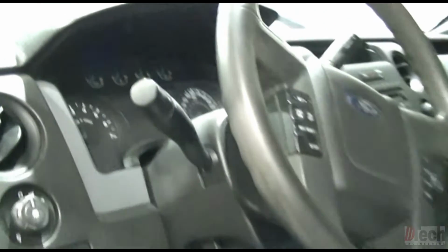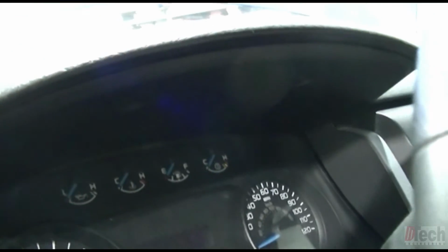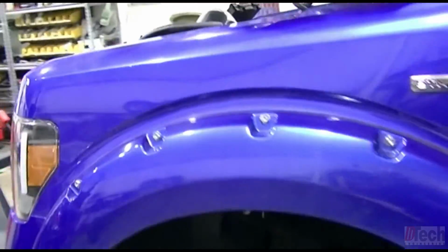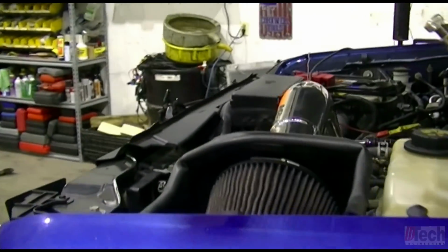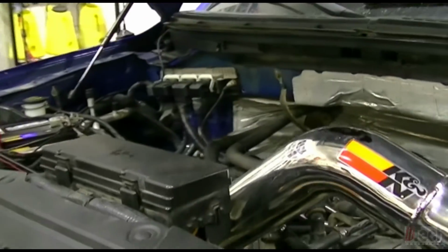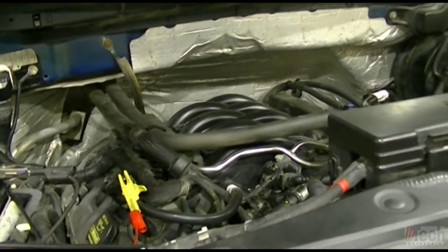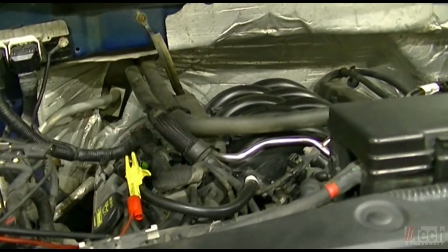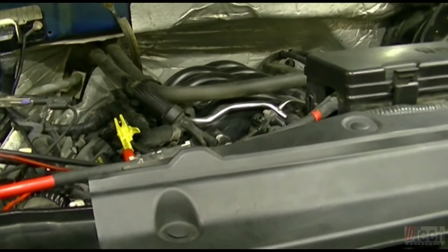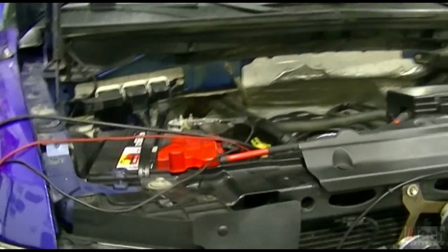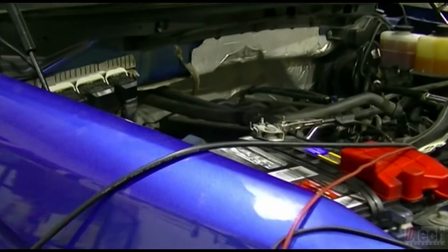As far as what this vehicle sounds like when it runs, we'll get you a shot of that. You can kind of tell it doesn't run terrible. It's not like a dead hole type of misfire. It's sort of a slight stumble. And so I'm letting it idle. Again, like I said, we know number 8 intake valve seems to be the issue.